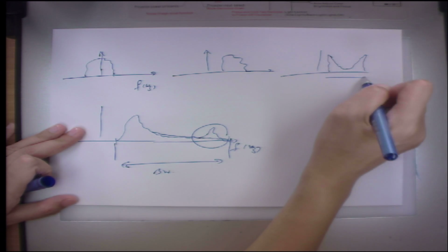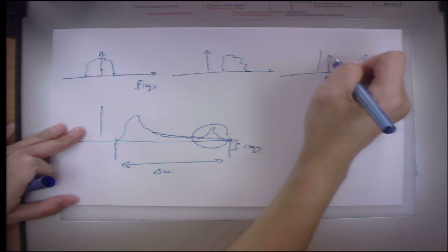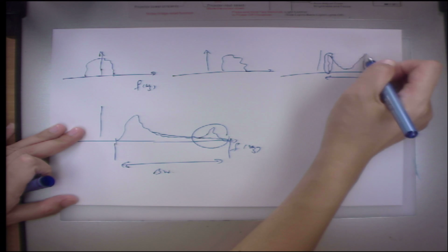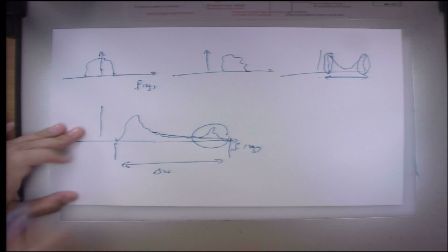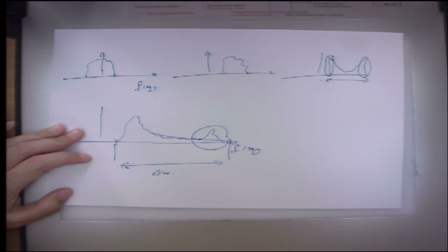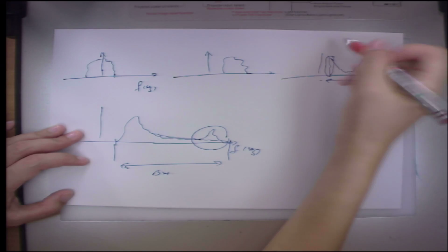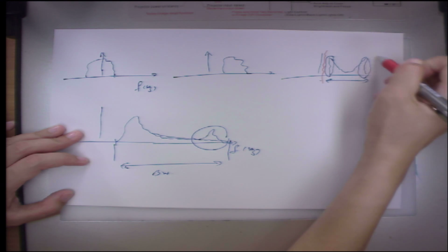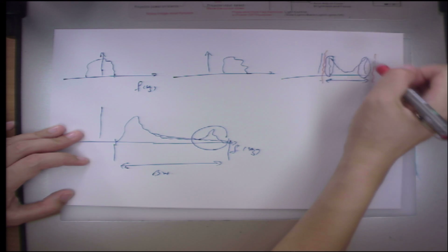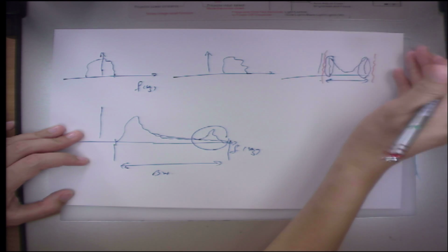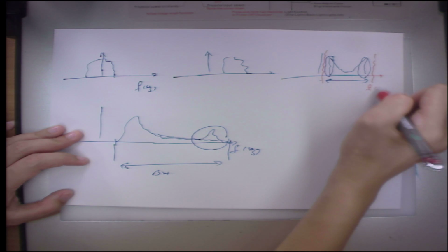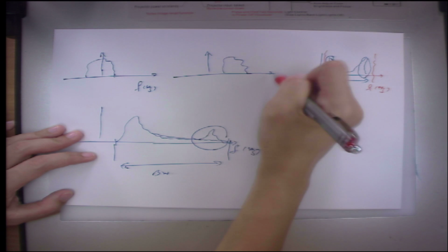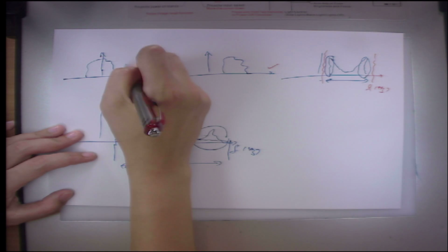And this is also not very good because the power is at the edge of the bandwidth. So maybe you have to give a wider bandwidth than the spectrum, because you don't want this one to be at the boundary; it will spill over to the other side, to the other channel. This one is good. This one is also good.